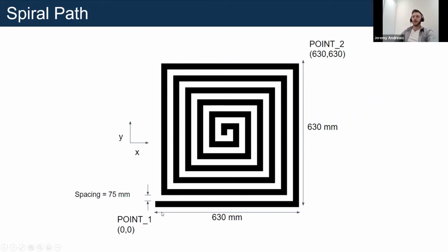So looking at this, what we have to do is get the machine to trace a path first along the bottom outer edge, the right outer edge, and then as you start going to complete the other edges, to create a smaller and smaller square pattern as we get towards the center. So this can be accomplished using machine logic, and I'll be showing how to do this. So to do this, there will be a few extra steps that will be needed. First, we'll be introducing variables, and then later on using loops as well.